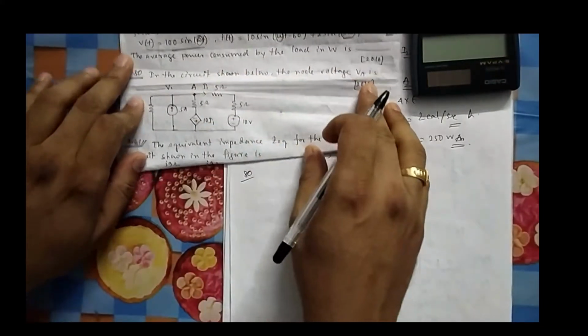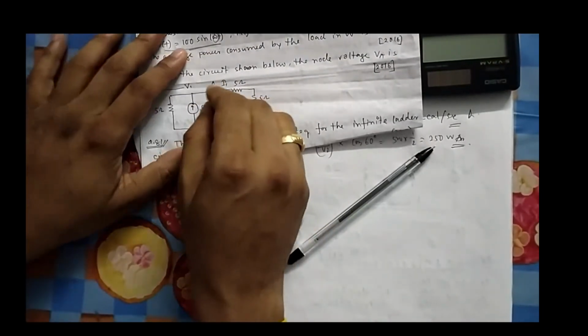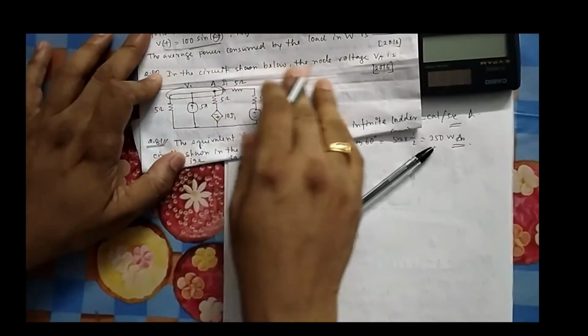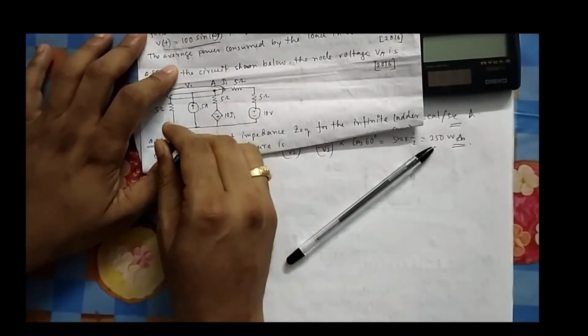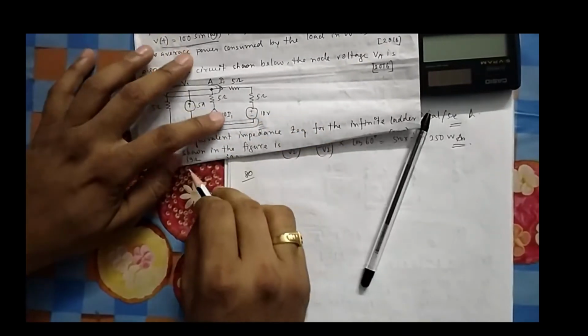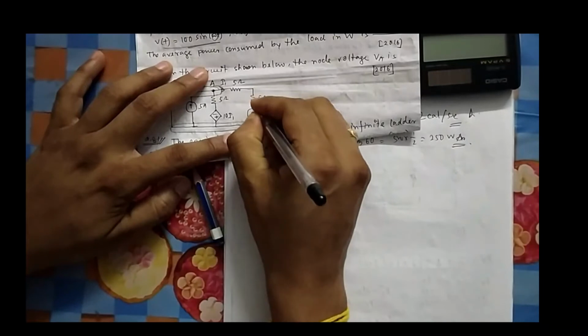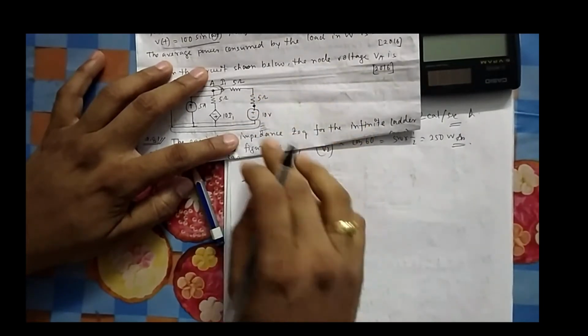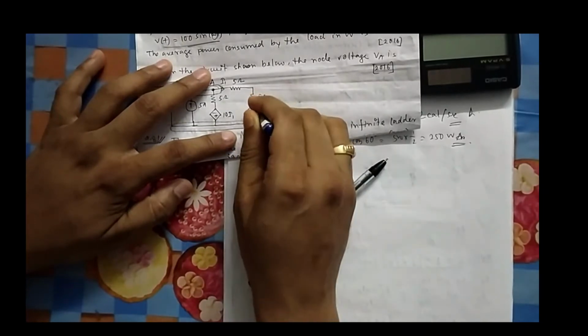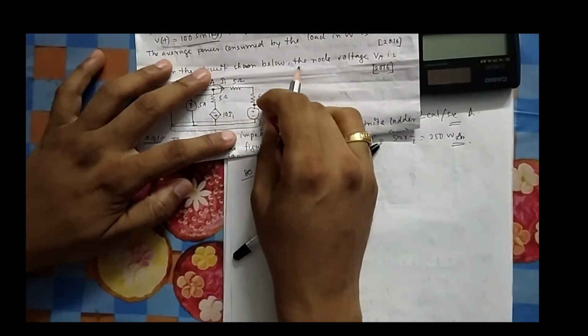In the circuit shown below, the node voltage VA. So it is a simple circuit again. Node voltage, this voltage they are asking. Okay, for this voltage, let me take nodal analysis. So this node I will make as a reference node. And I will make this node also a special node. I can make this one a node, but why am I making this one a node? Because here I know the voltage, 10 volt.